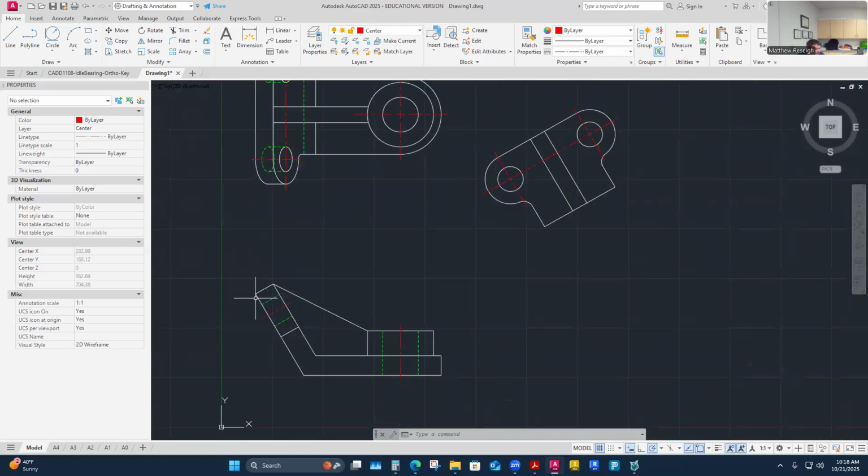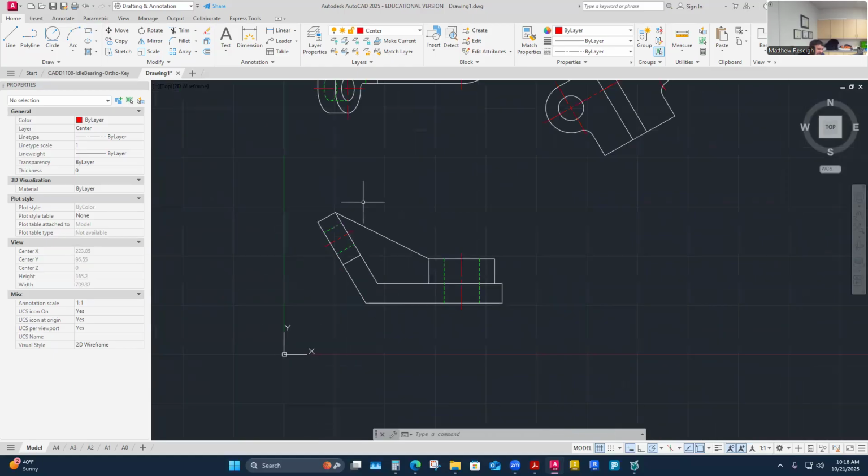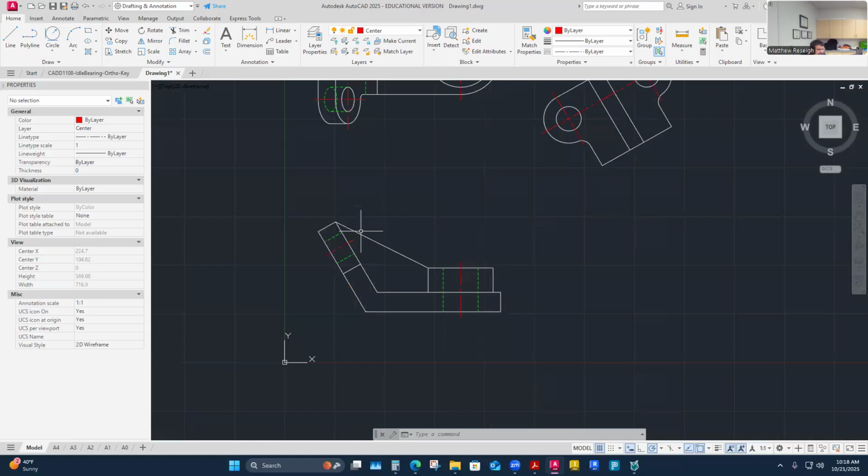The surface is here and it's not aligned to X and Y, so maybe it's not a great thing to pull dimensions from either. They'd be an aligned dimension, which in ASME we try to avoid. It's not that we can't put them in, but I'm going to try to do point to point X and Y, to locate edges and to locate things. I do X and Y type coordinates, point to point.